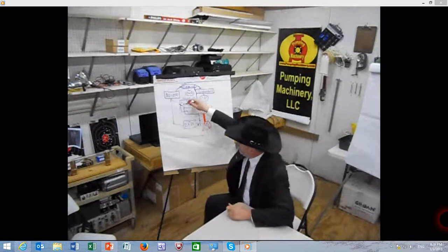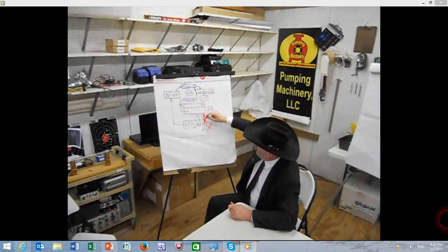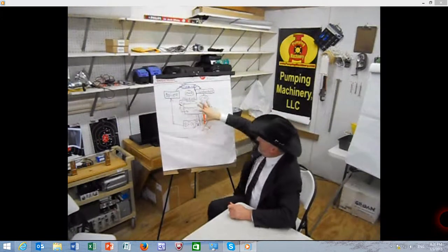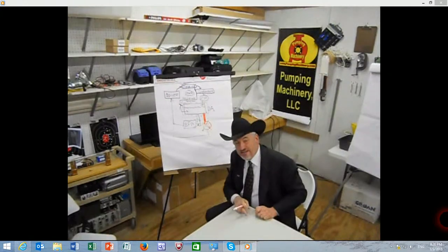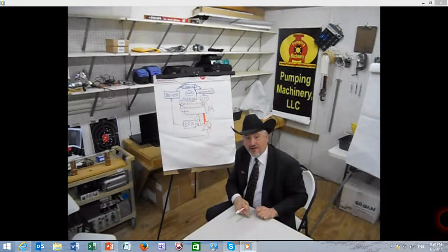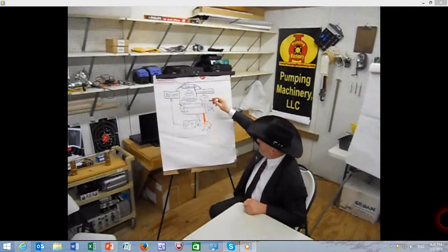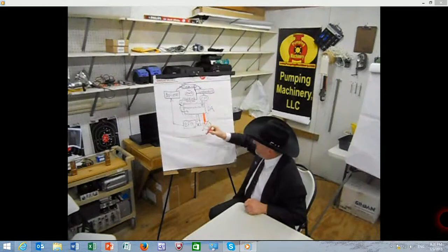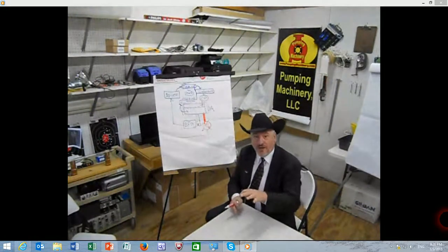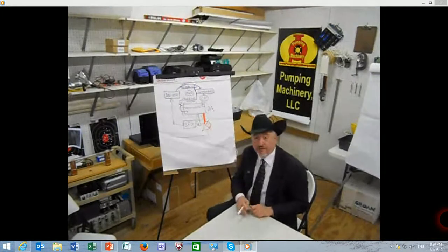We can think about a deaerator and a portion of the pipes as a so-called control volume, which is essentially constant volume. We can theorize that it is constant volume. There are connections. This, of course, is closed for the steam, but there's a connection open to the condensate pumps and the boiler pump. But the vapor cannot readily go through them. It has to first get to the water that connects the pumps.